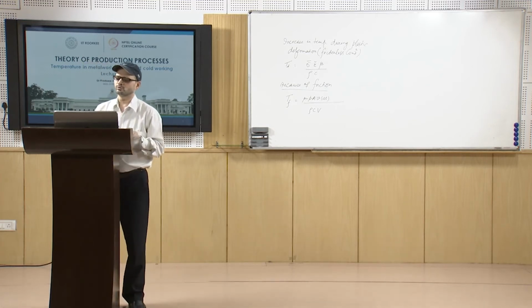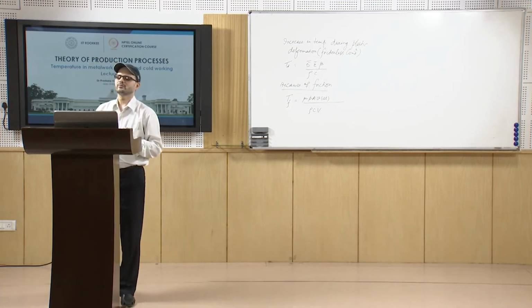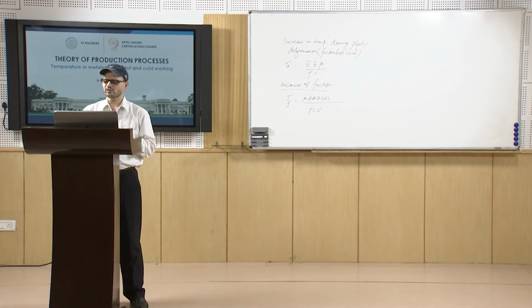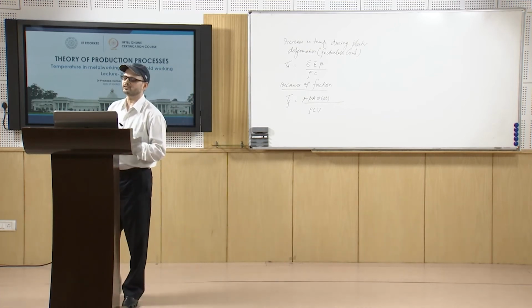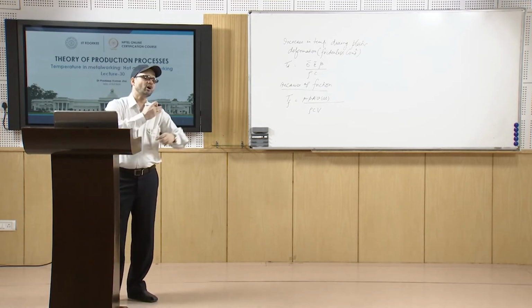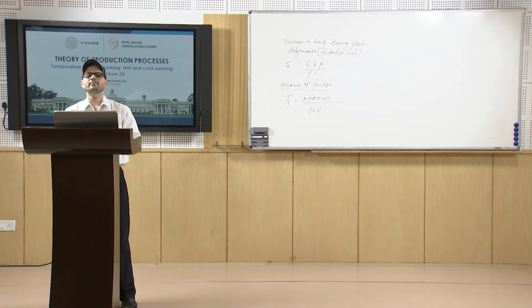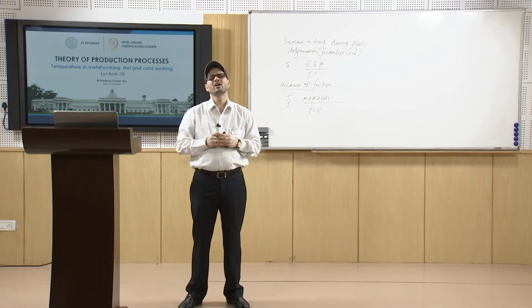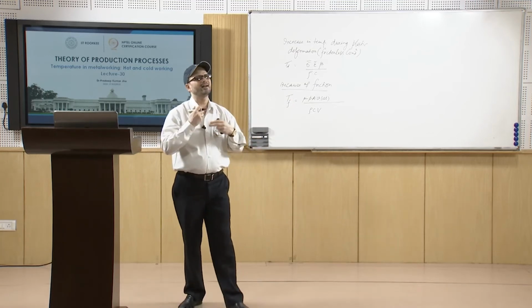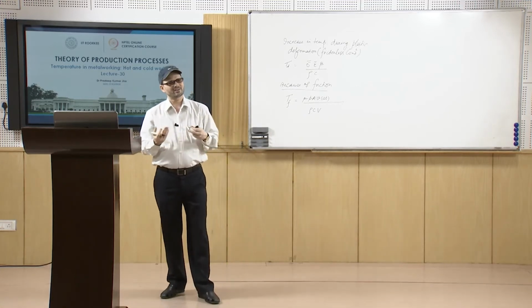Now, again coming to the different aspects of hot working, as we discussed, because of the rapid diffusion in hot working, that aids in decreasing the chemical inhomogeneity. What happens is that since hot working is done at a higher temperature, there is diffusion at a higher rate at those temperatures, because the rate of diffusion will be more at higher temperatures.